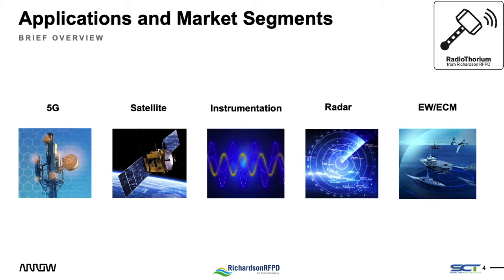Satellite communication is another market that benefited from access to K-band spectrum and therefore to higher bandwidth communication. One good example that comes to mind are the LEO constellation deployments that went through the roof in recent years, and here I can list SpaceX, OneWeb, and Telesat's Lightspeed. Our unit would only cover the SATCOM uplink path from 27 to 31 GHz, but that will take care of both the commercial and military spectrums.